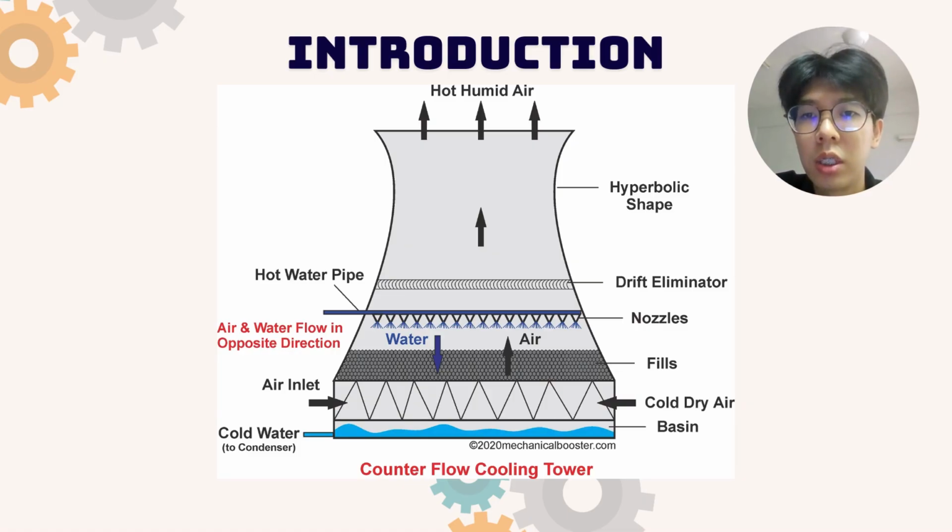This evaporation steals heat from the remaining airflow. The result is the air getting cool and humid. And the driving force for this process is the difference in water concentration. The job of a cooling tower is to reject heat from industrial processes, whereas a humidifier adds moisture to the air of a room.